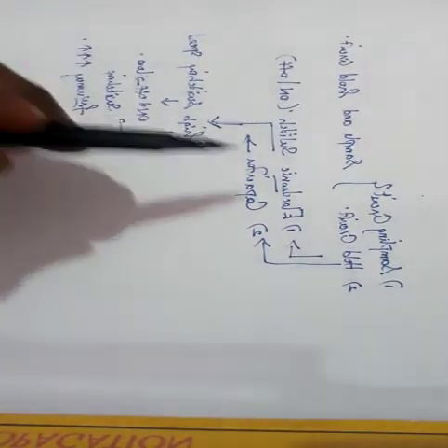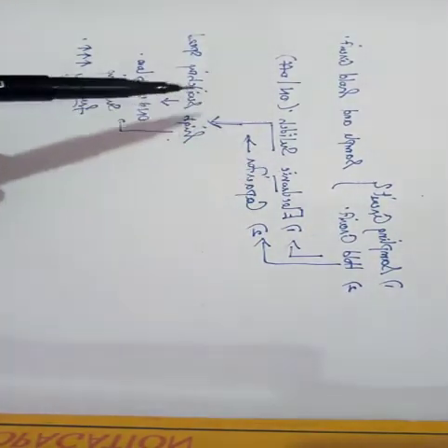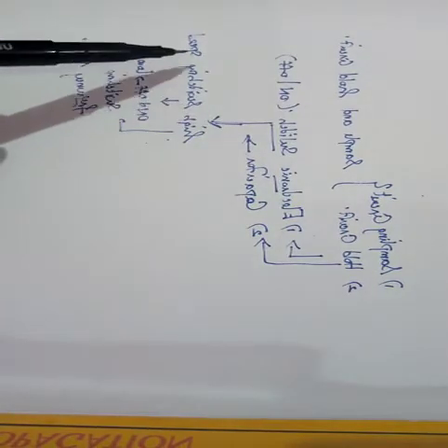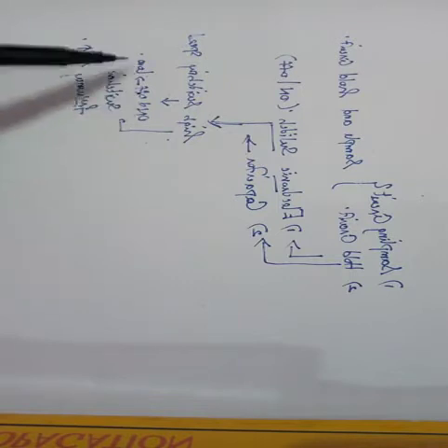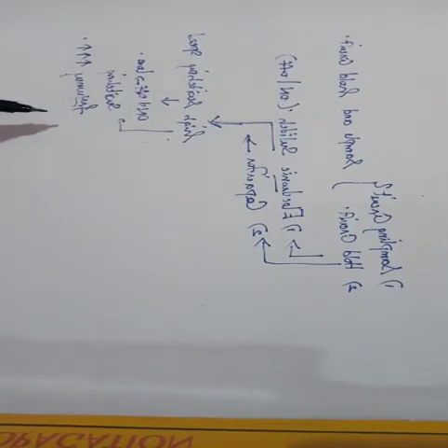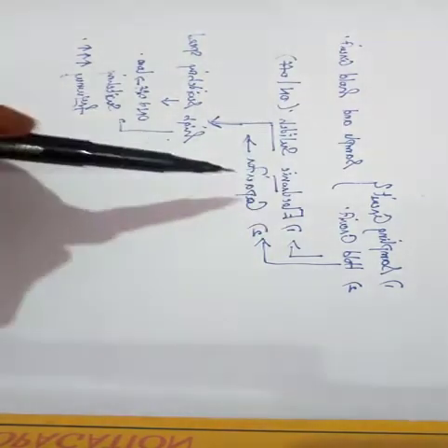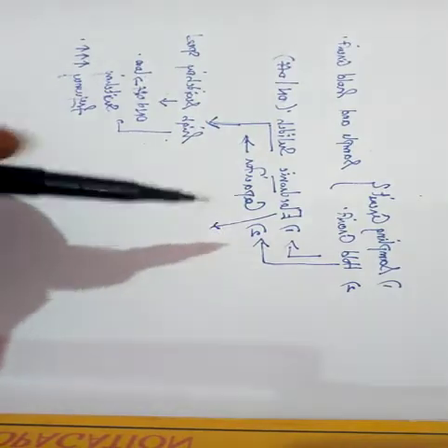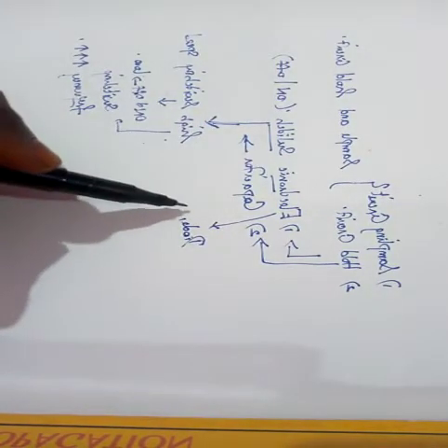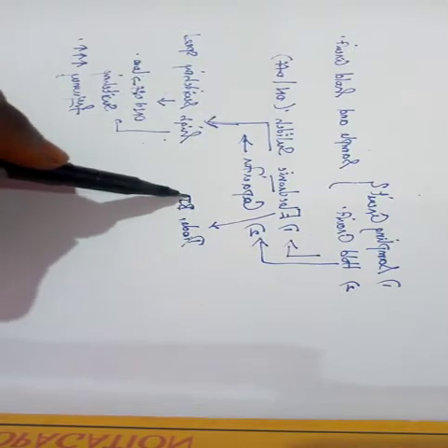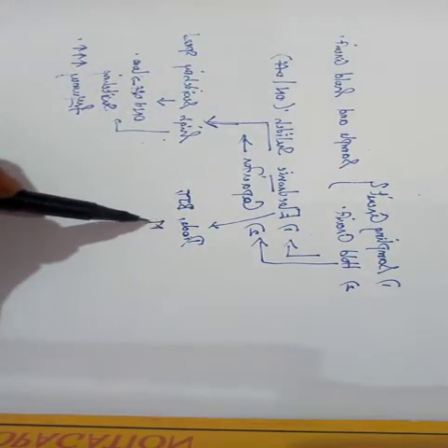Choose an electronic switch whose switching speed is high, that is, the on and off time should be low, so that, as frequency and time period are of inverse nature, the switching frequency would be very high. You know the basic electronic switches: you can use a diode, a transistor, that is a BJT, and even MOS switches.